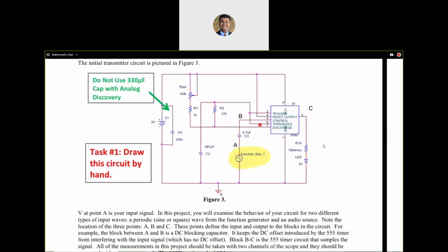On pin 6, we expect two resistors. There is one resistor R2 which is fixed. However, there is another resistor which is a combination of two resistors, as you can see. One is a potentiometer, a 100K potentiometer. So by using a knob or a screw, you can turn this wiper one way or the other so as to increase or decrease the resistance between 2 points, point A, point B. And the other resistor is fixed, 1K resistor.